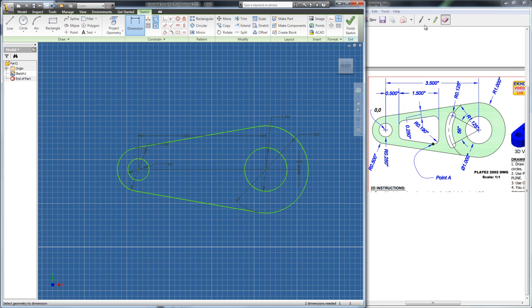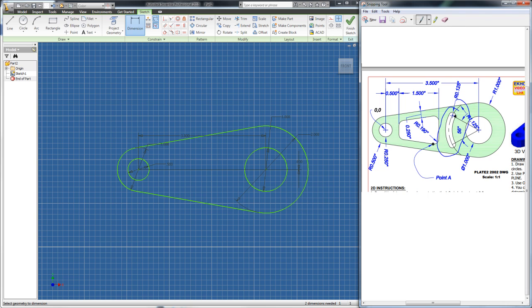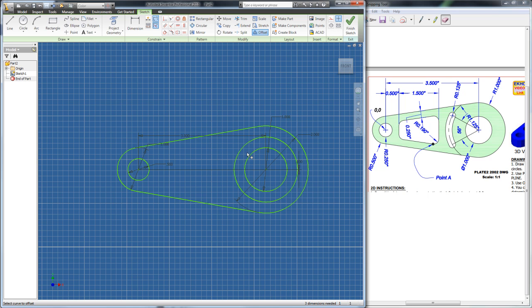Okay, now let's work on this piece here. So this is going to be based off my intuition using this software, but you'll pick these tricks up, sort of basically making construction lines first. This one's going to be diameter of 2, diameter of 2.25, a diameter of 2.5. I'll trim it so you get a better idea of what's going on here.